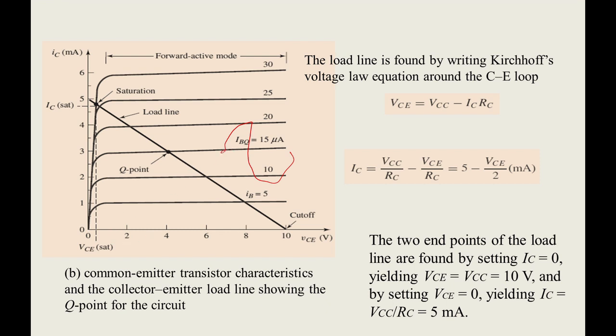So this is the quiescent point. I am saying again, the Q point is the point at which the signal starts to flow; above it, the AC signal flows. That is called the operating point. When I fix the quiescent point, you get linear operation. But due to some external parameters, it may shift upward or downward. When it moves nearer to the saturation or cutoff region, some part of the signal will clip out. We want to recover from that condition, and for that reason we go for DC biasing circuits.